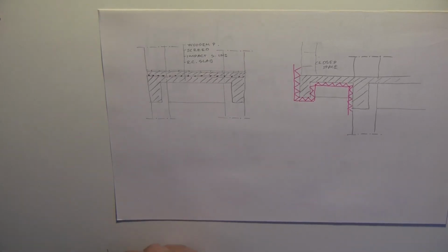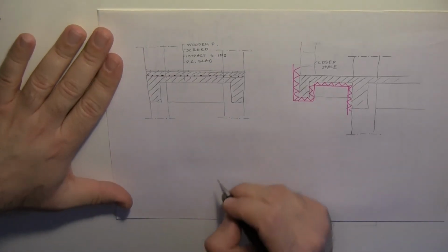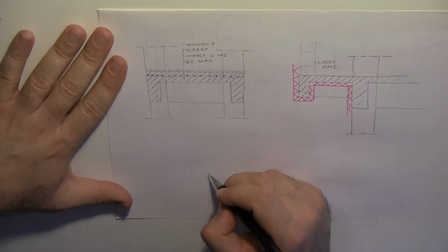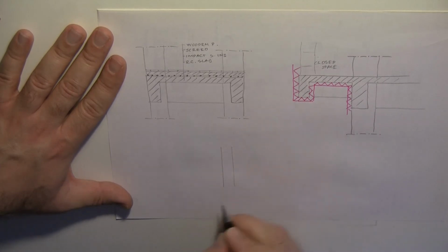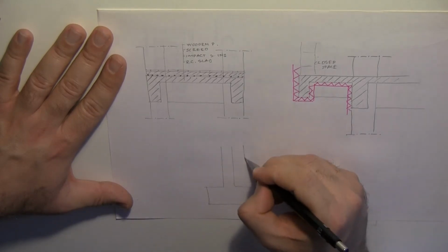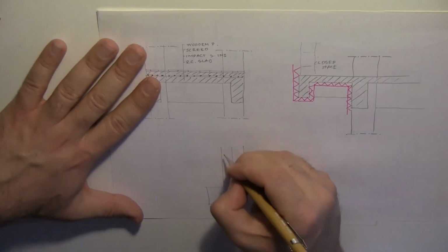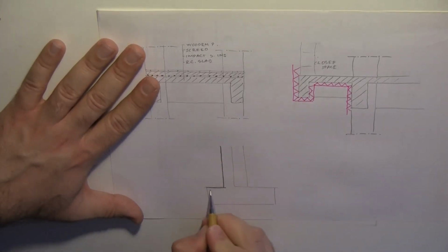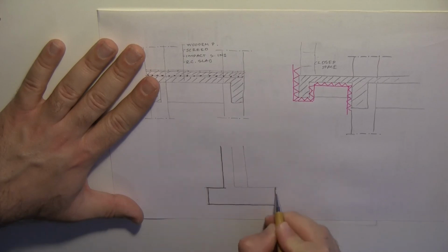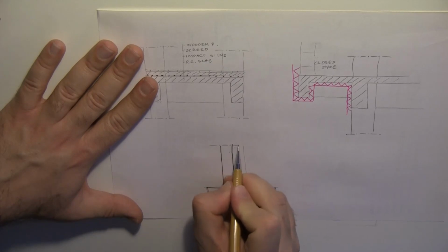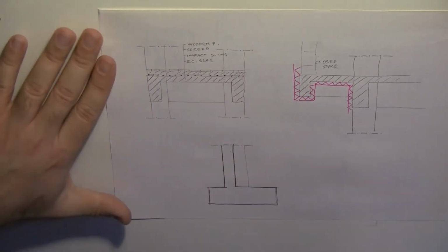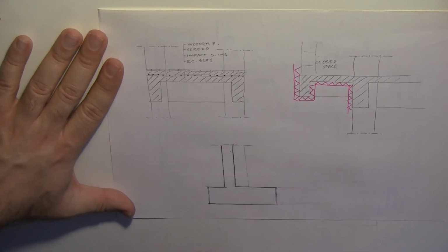And the floor on grade type of floors, they are floors which are usually located over the foundations. Let's say that this is my basement wall, this is my strip foundation, this is the column in the background. I'm going to draw them thicker. This is my strip foundation like this. And here is the dashed and dotted line. And what do I have? I have the strip on the elevation like that.